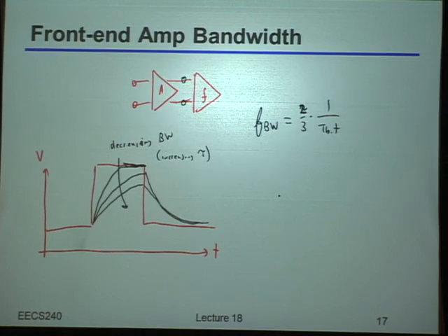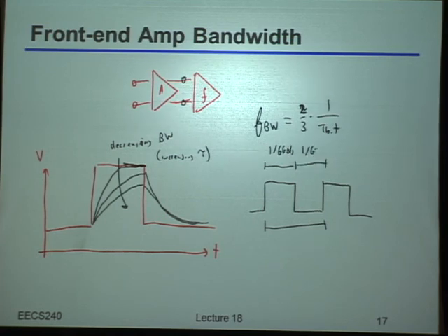Yeah, alternate zeros and ones. So if I've got a 6 gigabit per second signal with alternating ones and zeros, the period here obviously is not at 6 gigabits per second. It's actually at 3 gigabits per second, or 3 gigahertz, I should really say to be accurate. Right? Because obviously this is 1 over 6 gigabits per second. That's also 1 over 6 gigabits per second. So on the net, you of course get 3 gigahertz of bandwidth.